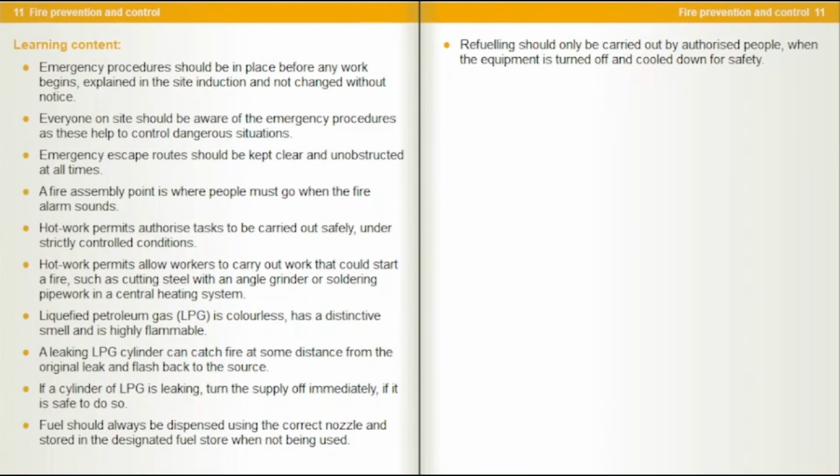Fuel should always be dispensed using the correct nozzle and stored in the designated fuel store when not being used. Refuelling should only be carried out by authorised people, when the equipment is turned off and cooled down for safety.